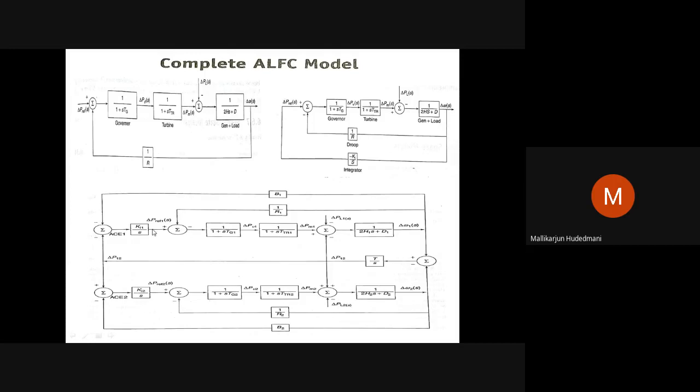Therefore, revision of the reference point becomes inevitable. Revising the reference point makes the governor re-energize with an additional operating point band, so it may bring the deviation to 0. Then who will do this reference point control? Some controller has to be there which will do this automatically. That is done by the integral controller.